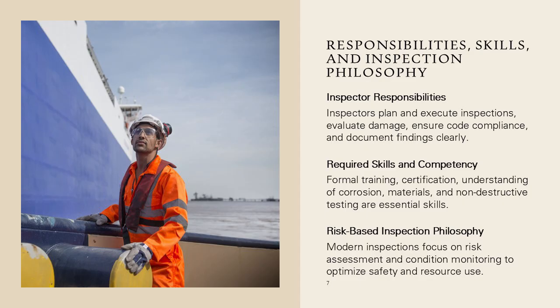Modern inspection philosophy emphasizes a risk-based and condition monitoring approach rather than reliance on fixed intervals alone. This means inspectors must be able to assess likelihood and consequence of failure, understand historical inspection data, and focus inspection efforts on areas of higher risk. Such an approach improves safety, optimizes inspection resources, and supports informed decision-making regarding continued operation or maintenance planning.